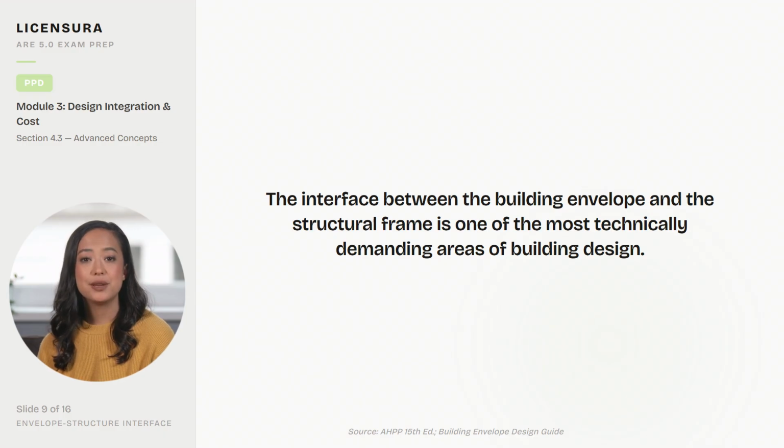The interface between the building envelope and the structural frame is one of the most technically demanding areas of building design. This is where thermal bridging, moisture management, air barriers, and structural connections all converge. The exam tests this heavily because failures at the envelope structure interface produce the most expensive construction defects in commercial buildings.